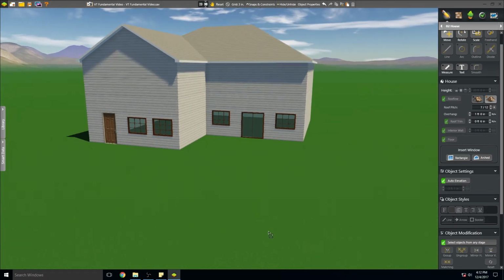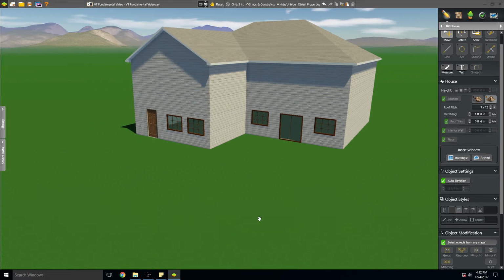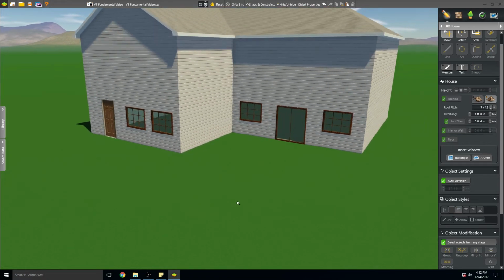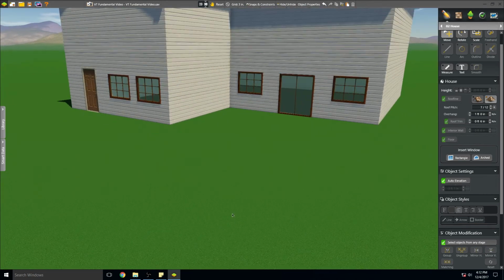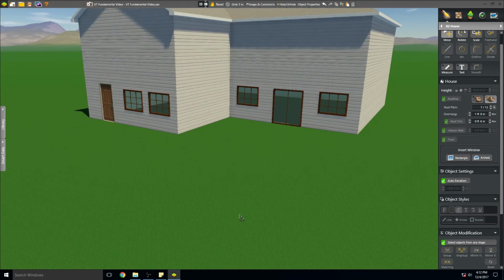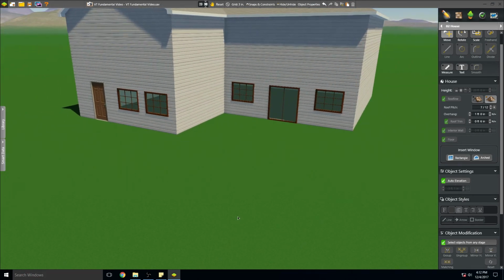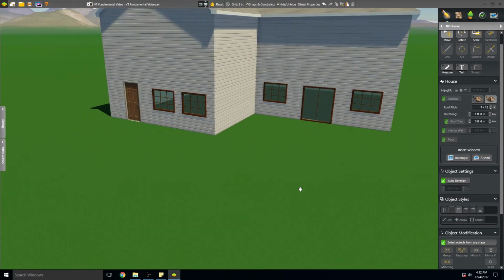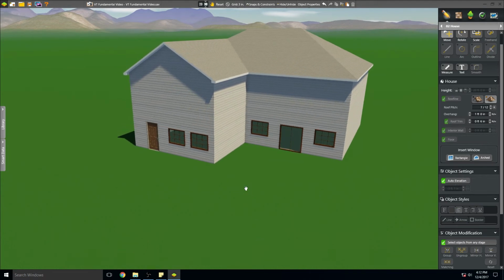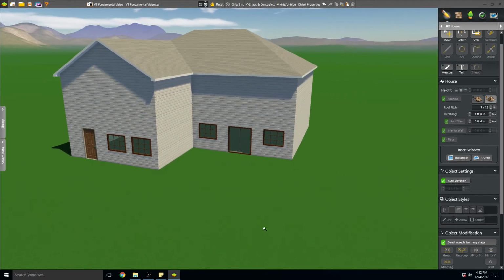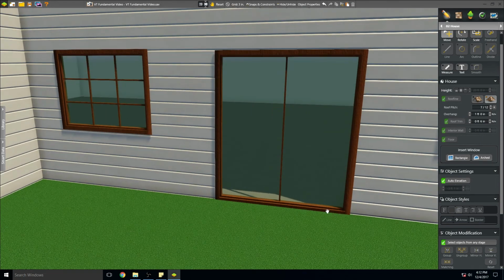All right, so I just want to kind of review the navigation tools that we learned in 3D. We can zoom in and out with our right mouse button or a middle scroll wheel. You can rotate the angle of your perspective. Also, you can press down on your middle scroll wheel like a button and pan. I use this a lot. Like if I want to zoom in on the door, I can zoom in and then pan over and get a really good look at it.